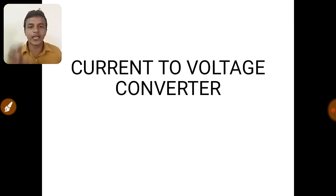For example, let us take a photodiode and a DC motor. The photodiode converts the light signal, the intensity of light, into an electrical signal. Let us consider an example of a solar tracker. The photodiode is a photosensor device, and there are a lot of photosensor devices like the photoresistor, phototransistor, and photodiode. What does this photodiode do? It converts the intensity of light into the equivalent electrical signal, and the electrical signal is in the form of current and not in the form of voltage.